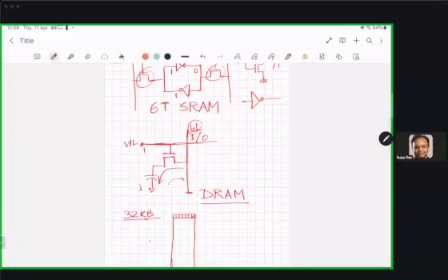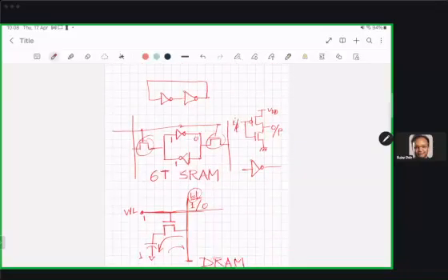It is connected to 32 such transistors. Each of these 32 transistors will have their bit line, and I will initialize those bit lines, and accordingly I will read or write. Similarly, here if it is a SRAM, then this row word line select will select that particular cell.